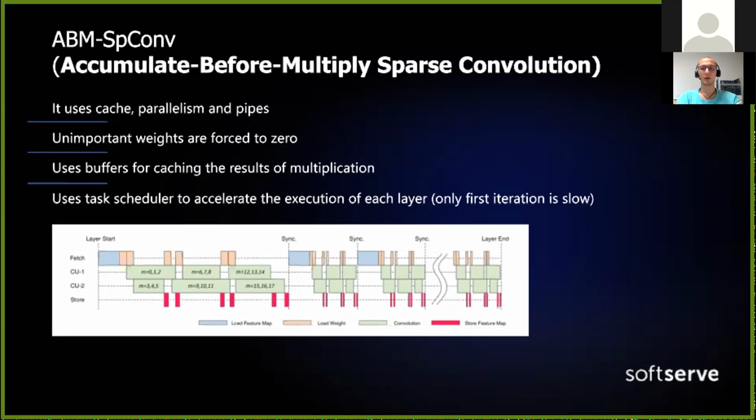They have pre-processing of the convolution that calculates the number of entries of each number in the input matrix, counts it and sorts it in some way, and saves these results in a table on the on-chip memory, so that when the model sees something like multiplication of two known numbers, it just takes the result from the table and doesn't do the multiplication.